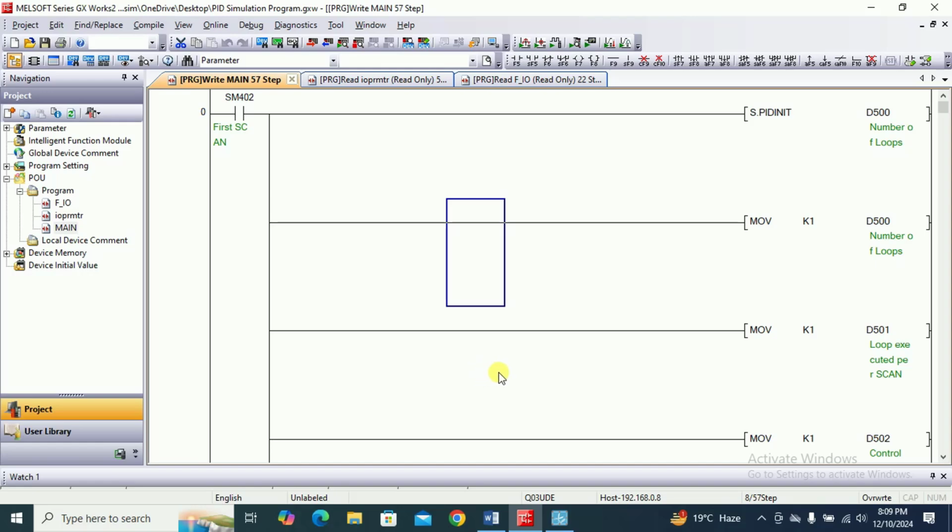So for interfacing this PID input-output data with the input-output data of the level process station, this input-output data will be converted into OPC format. This can be done using the OPC tags in the Mitsubishi OPC server software.